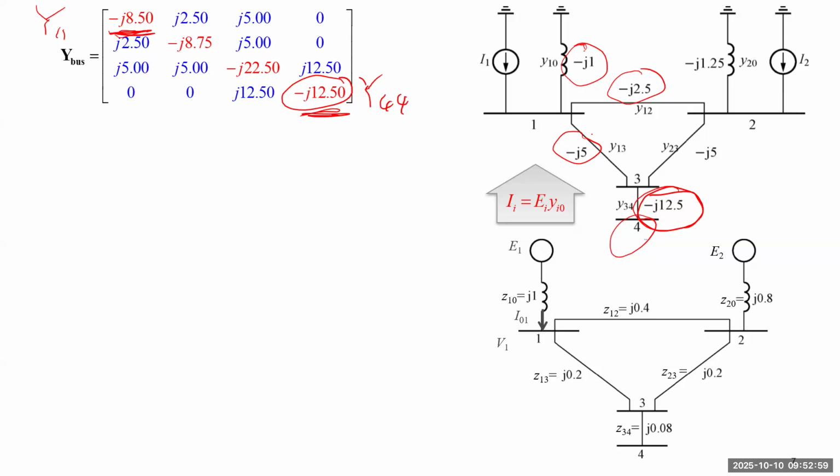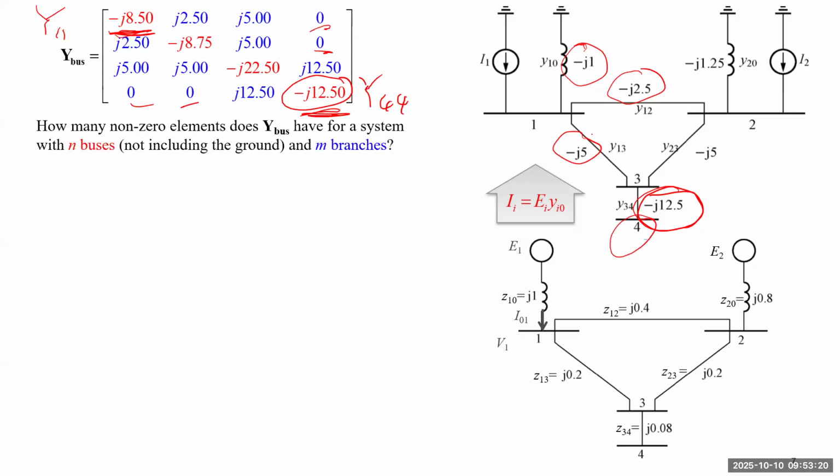All right. For the off diagonal element, that will be pretty simple. If there's a direct connection, you just take the negative value of that admittance. If there's no direct connection, you basically just take 0. So this matrix is symmetric, which means the transpose of the matrix is itself.